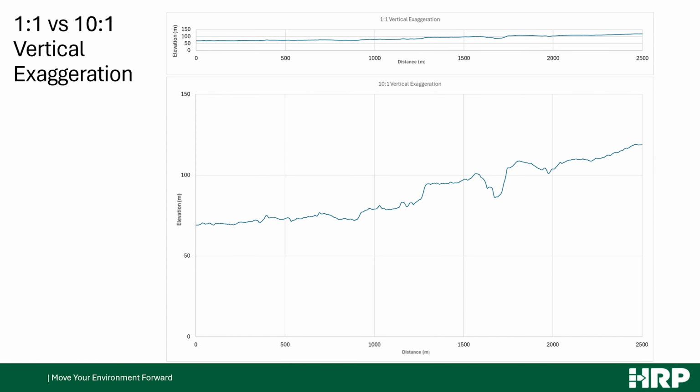So I wanted to show you the examples between a non-useful vertical exaggeration of 1-to-1 and then a 10-to-1, which in this setting does have some utility. The top example is a 1-to-1 vertical exaggeration, meaning that for every inch you travel vertically, you travel the same distance horizontally. At this exaggeration, you have a hard time seeing the surface features because the Earth is, at least for our investigations, always going to be much longer in distance than it is deep.